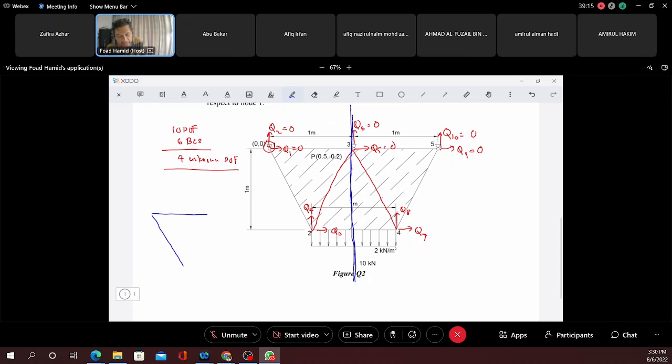study half of the plate, which is this one. But remember, in the project, it says that you can make it symmetric, but you need to have the appropriate boundary conditions. Before this, we have 10 degrees of freedom, we have 6 boundary conditions, and then we have 4 unknown degrees of freedom, right? But we do not change anything. We do not change the boundary condition.